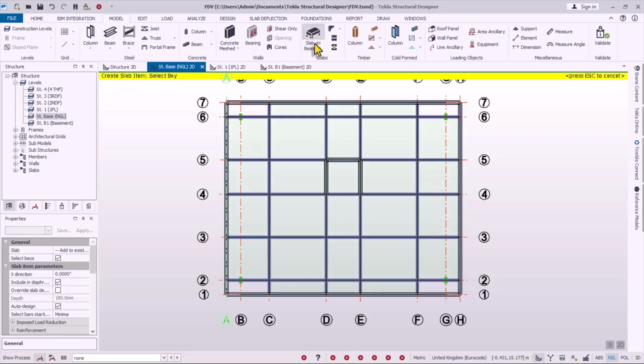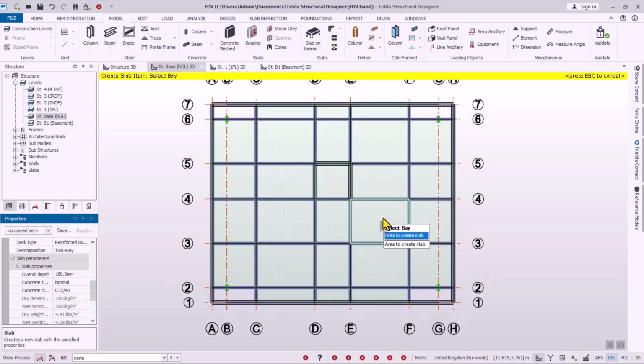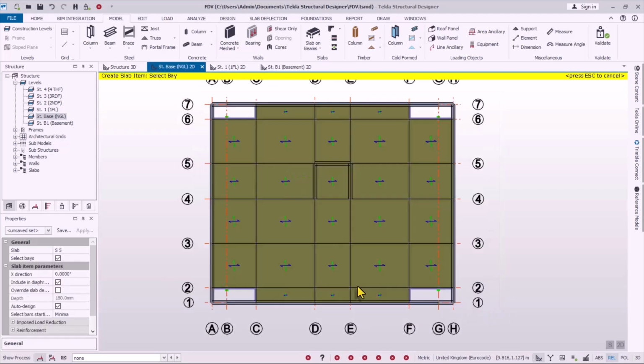Come and click on the beam option. You can see everything is good. It's not showing red alert right here. So up here, I will have a new slab. I go by the slab thickness that we just set, which is 180 millimeters. All right, so I can now do a window over the grid intersection, release my hand to have the slab placed successfully, just like this.